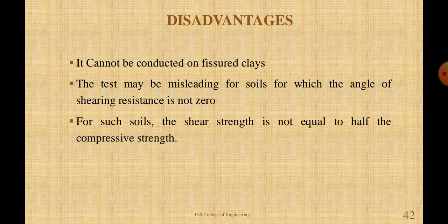Then the disadvantages of unconfined compression test. It cannot be conducted on fissured clay. The test may be misleading for soils for which the angle of shearing resistance is not zero. For such soils, the shear strength is not equal to half the compressive strength.